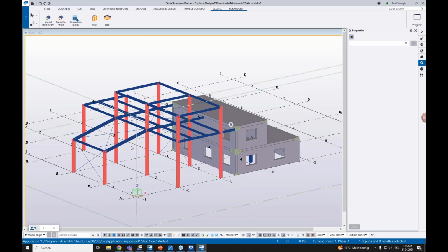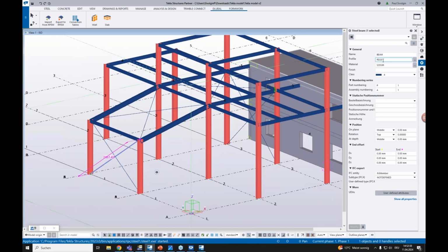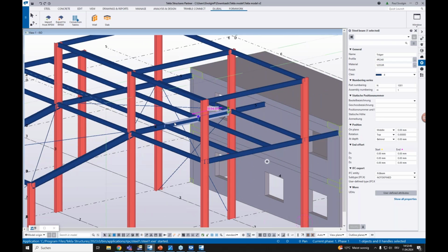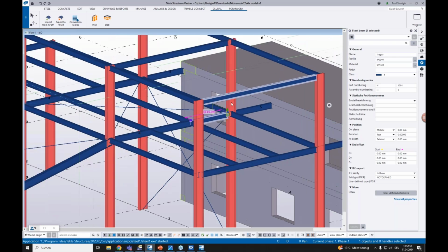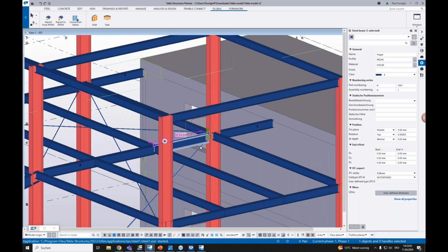Okay. So you can see the bracing is now added in the structure. We also have a profile we defined in RFEM and also the material we defined in RFEM. We also see that these sections here are updated to the IPE 240. And we also see that already defined components remain in the Tekla model, even if we updated this cross section in RFEM.